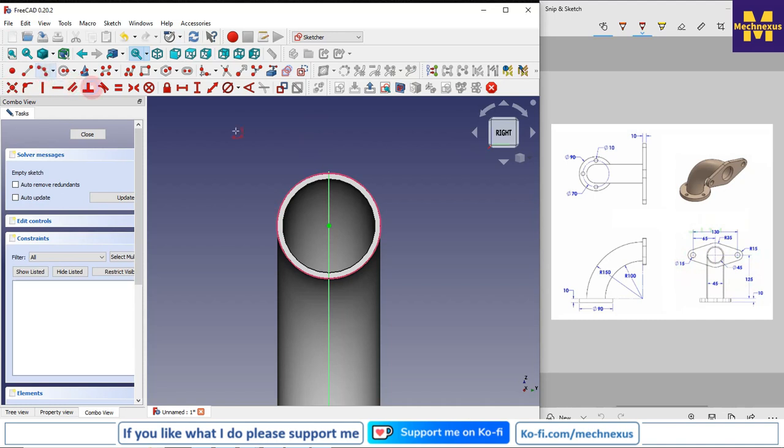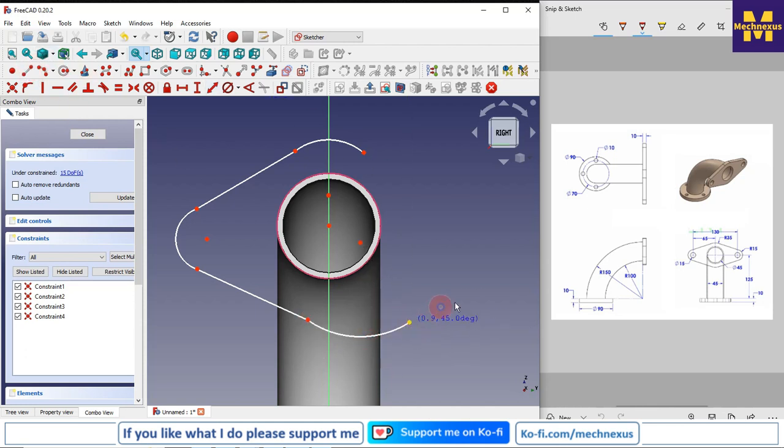So for this I will select a 3-point arc, then I will select a line, then again a 3-point arc, then again a line, then again a 3-point arc, then again a line, from here also a line, and then a 3-point arc. So this is just the basic profile. Now we will constrain it.